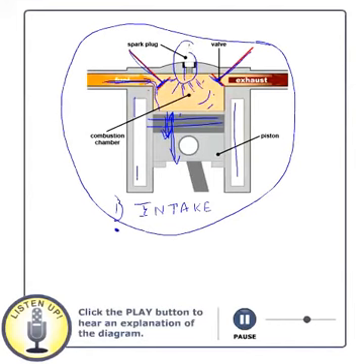The first stroke is intake. The second stroke is compression. And the third stroke is the power stroke. That is the stroke that gives us the power from this engine. And for the first stroke and the second stroke, we have to supply the energy that is required to bring in the oxidizer and fuel, and also to compress.